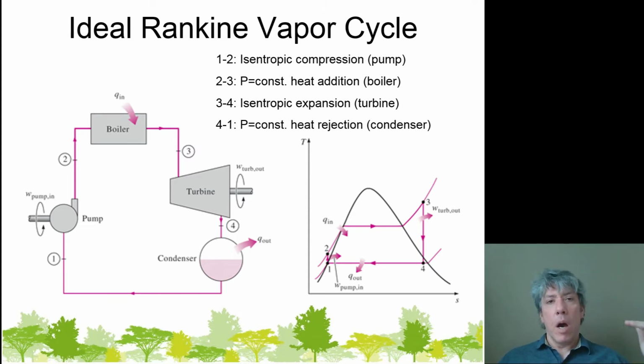So we've got to go all the way from compressed liquid, where we increase the temperature, a sensible energy change, to the point on the left of the vapor dome, saturated liquid, so that we boil it off into all saturated vapor, which is on the right side of the vapor dome at the saturated vapor line. Then continuing along that constant pressure line, we continue to add thermal energy to the now saturated vapor so that it becomes a superheated vapor at state 3. And so that whole line from 2 all the way to 3 is a constant pressure line.